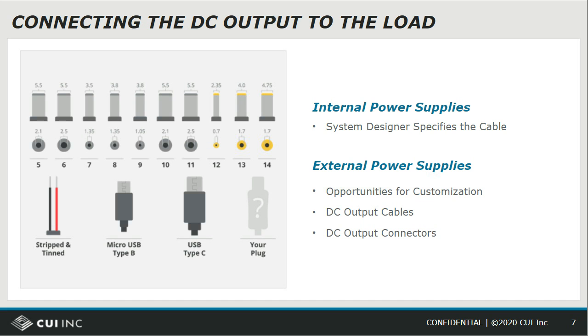It's a whole other discussion going into what the USB type C means, but suffice it to say, one of the things with the USB connectors is tradition says that there are specific voltages that one uses through a USB connector. So if you're using a non-standard USB voltage, you may choose not to use a USB connector. Another common connector for higher power applications is referred to as a DIN connector. And this is actually of German origin, but it's used worldwide these days.